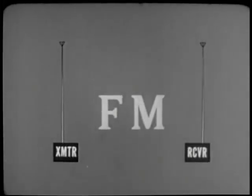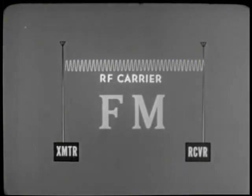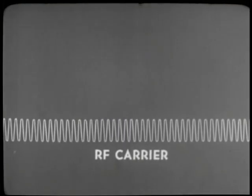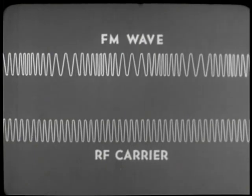The FM radio is not a miracle. It was, in fact, a logical development, a natural step forward in electronic evolution. Now, some of the facts about the evenly spaced, unmodulated RF carrier observed in our review of AM can be utilized. Interference does not affect the frequency of the RF carrier wave. Therefore, when intelligence causes the frequency of the carrier to change, the problem of hash and static is automatically eliminated.